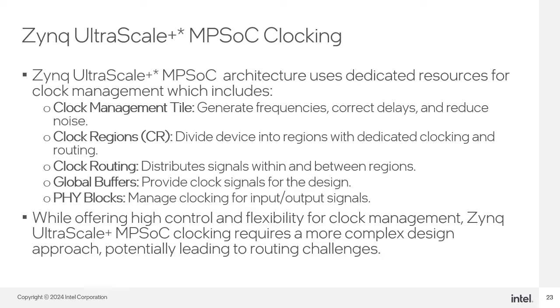The Zynq UltraScale Plus MPSoC provides dedicated resources for clock management, including the clock management tile, which is responsible for generating the operating frequencies, noise minimization, and latency corrections. The clock region in the Zynq devices allocates the required dedicated clocking and routing. The clock routing is then responsible for distributing the signals within the clock regions. The global clock buffers provide the clock signals for the design. The transceiver tile blocks manage the clocking for the I/O signals.